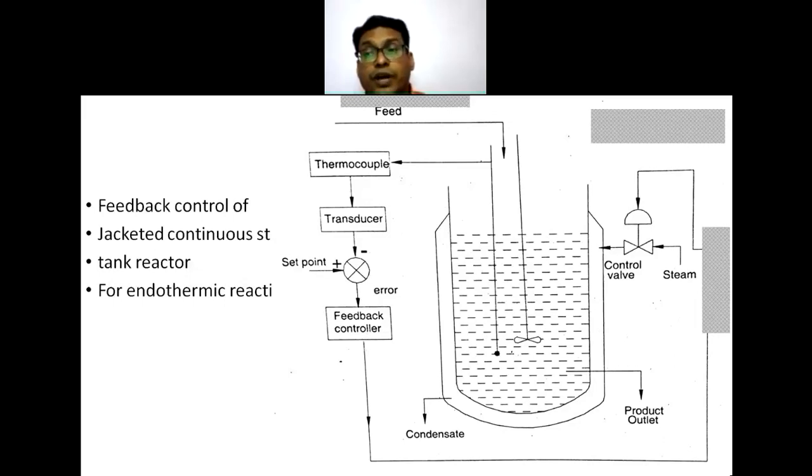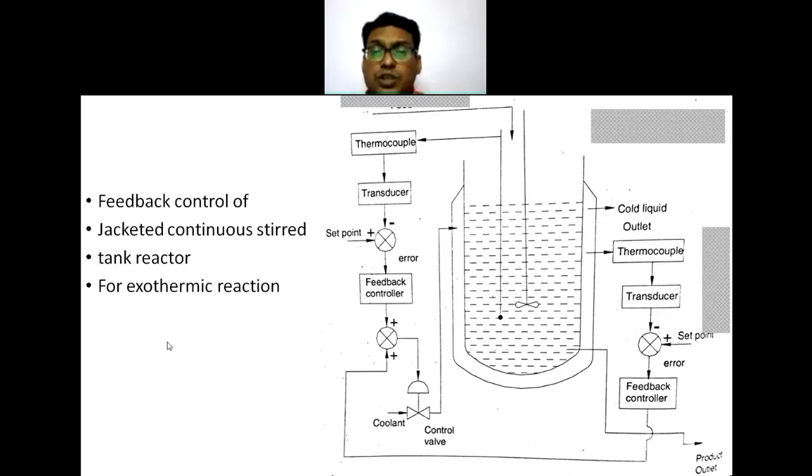That means whenever steam is used, the condensate will also be at the same 100-degree temperature. And that is why we always know the condensate temperature, that is 100 degrees Celsius, but in liquid form. And that is why we are definite about this outlet temperature of the steam. In the previous case, the exothermic reaction, we measured the outlet temperature.